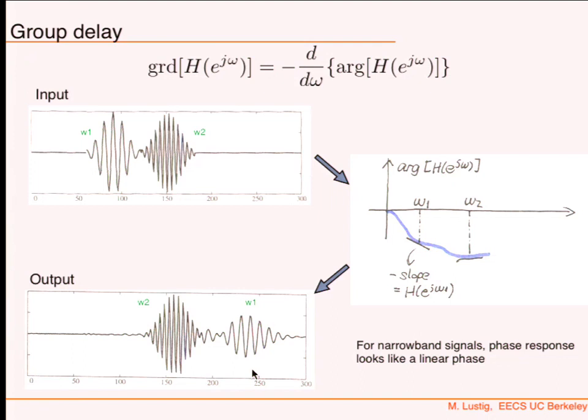Maybe there's actually a good reason to do this. Let's say our voice fluctuates over time. If I want to run it through an amplifier, it doesn't give good efficiency. I have to change amplitude very, very quickly, over and over again. Then I have to use a very linear amplifier to meet this, and it's not really efficient from a power point of view.